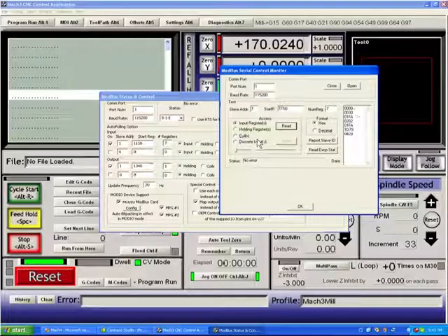Now you can also send data to a ModBus. We could, for example, here we type in the data that we're going to send to a ModBus device, and you can see I can just type a bunch of zeros or leave the random data. We're going to send to the holding registers starting at address 1040, which is the memory address of Peter's Mod.io board on its output registers. So we hit read,